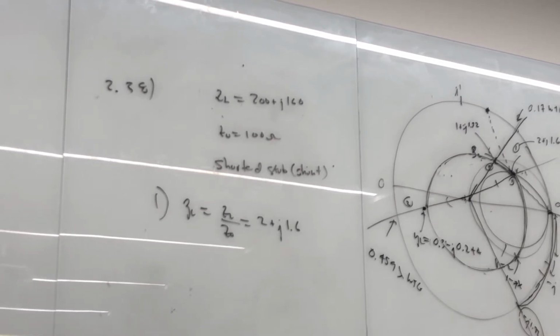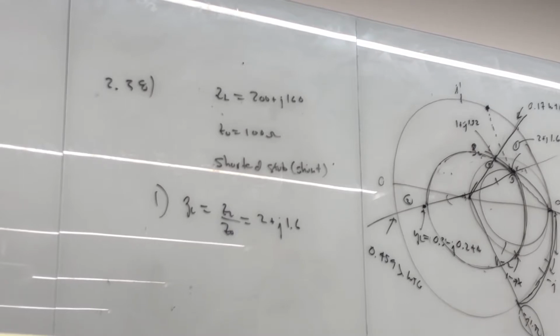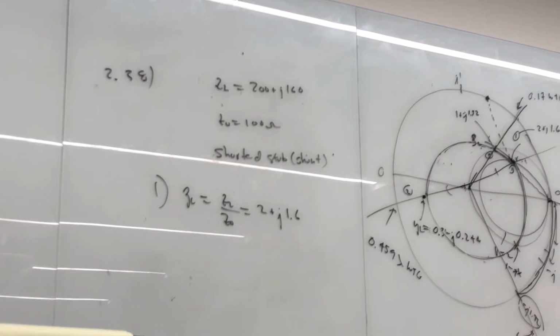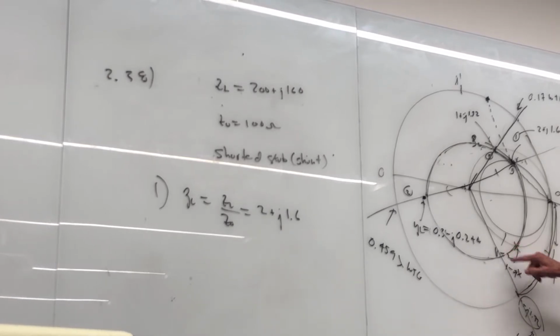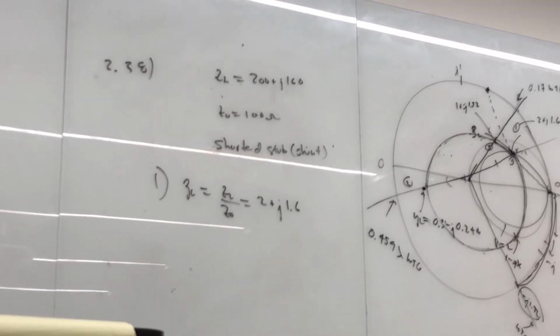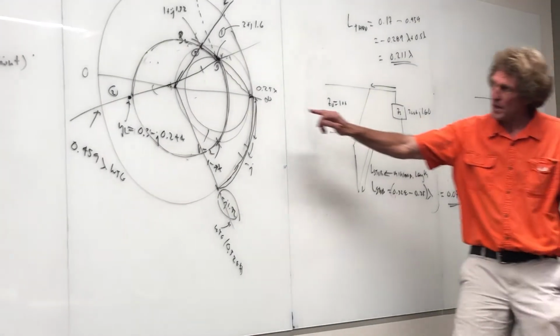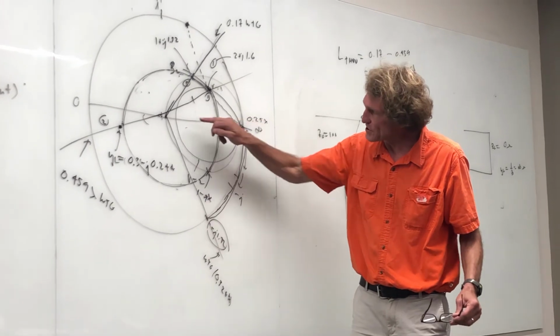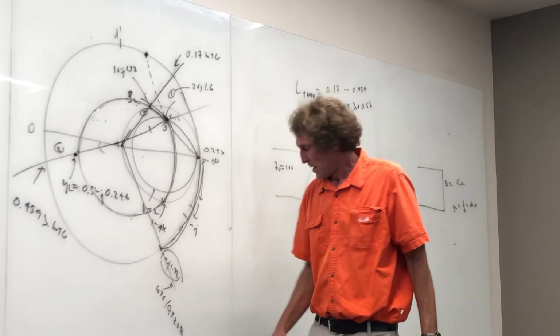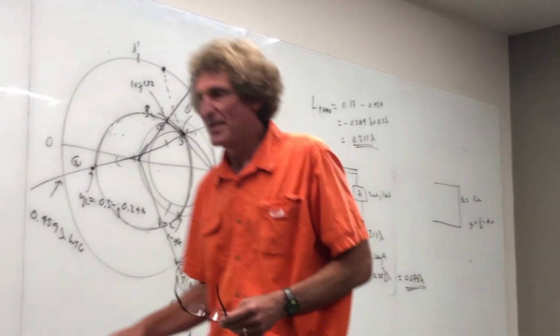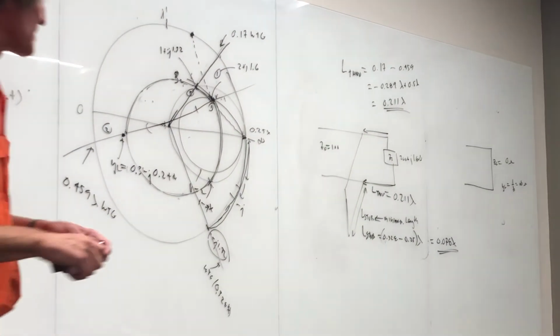Oh, okay, I did it from the point. No, you don't move on the circle that you drew earlier, you're moving right on the rim. This point right here has to be right on the rim. When we're doing impedance matching, we start here, we have 0, 1 over that is infinity, we're right here. We have no portion inside here, and now we're moving on the rim. All right, then it's 0.354. Okay, that makes my heart feel a little better. This is 0.354.